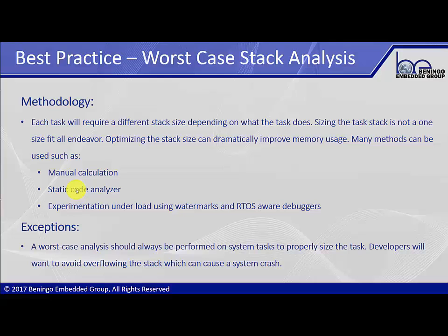So what I just want to mention is that a best practice for developing a real-time application is to perform a stack analysis on every single task in your system. Every task is going to have stack space allocated with it because it behaves like its own independent application. And sizing the task stack is not a one-size-fits-all endeavor.